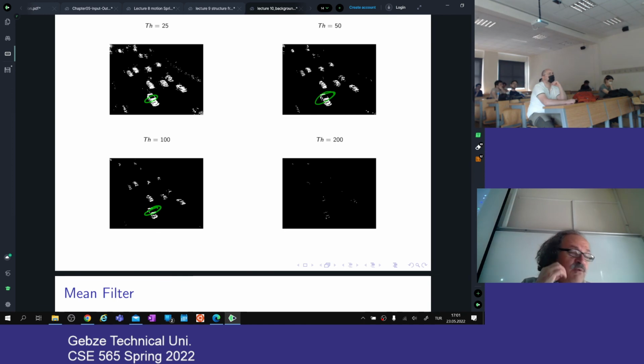Where do we have a motion detector? Very cheap motion detectors that you use at home work this way. They keep taking the difference between two frames. If there's a difference in terms of infrared signal, it just turns on the light. Many times it fails, but that's okay, this is very cheap. But for security applications, you cannot afford to lose one or two frames, so we have to do better.